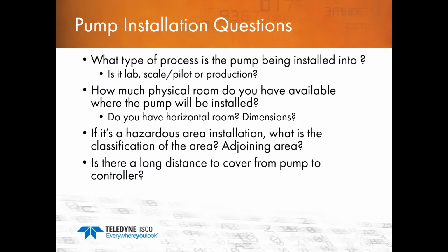In today's applications, it's not always just the pump. Sometimes you need to add a mixer to keep fluids in suspension, or you need to add a cooling jacket, or an external bath, or a pressure pot, or something else that would surround the pump to help the fluid or material you're pumping maintain the state you're looking for. So you really want to look at not just the room for the pump, but what else you might possibly need to keep the fluid or material in the state that you're trying to use it in.